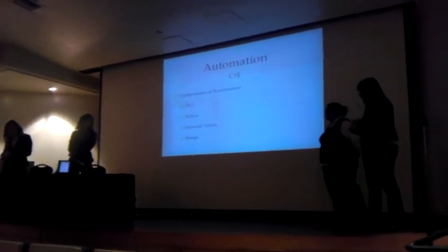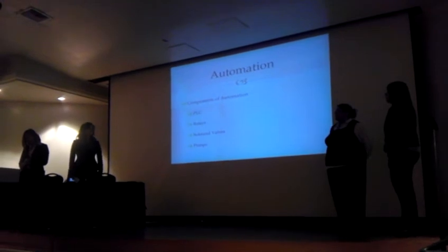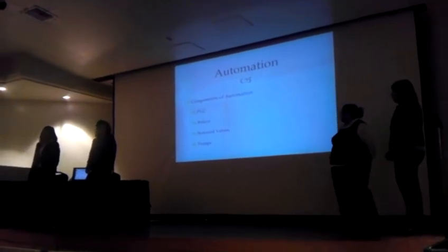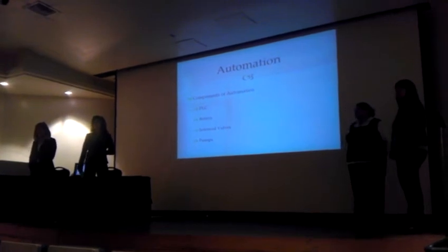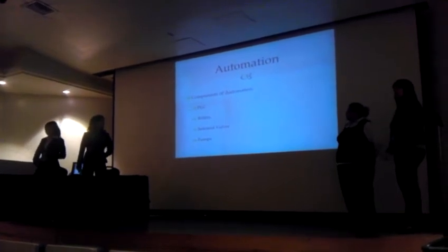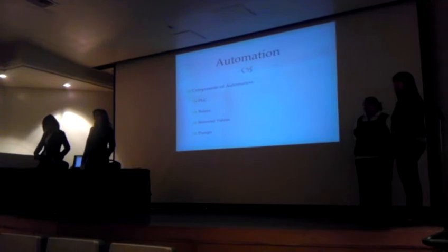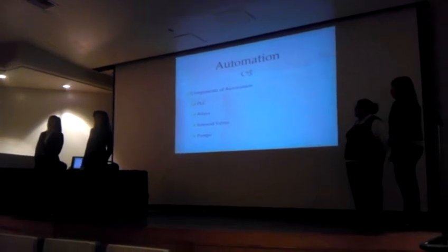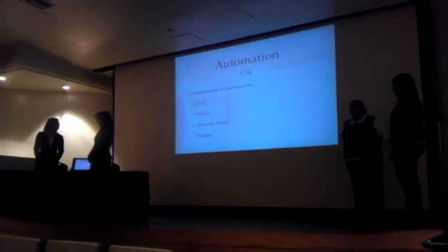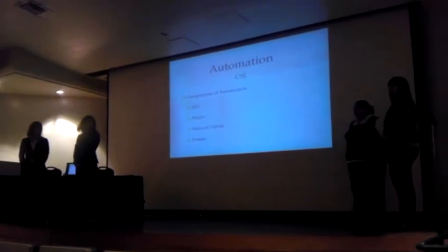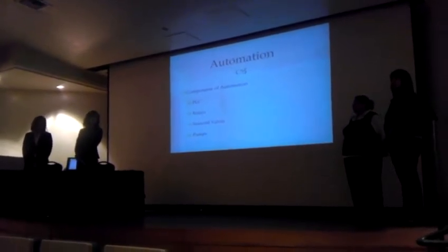As also part of the system, we were going to automate the system. Some of the components we have used in the automation is obviously a PLC. The PLC is communicating through a relay, activating the relays, and actually making our output devices, which are the solenoid valves and the pumps, actually work. Get them running and turning on and turning off whenever we need them in our system.